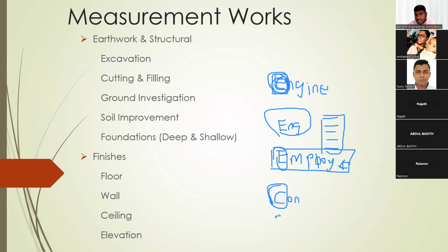If you put a small c, that will refer to other contractors, like subcontractors, nominated subcontractors, or whatever it is. So whenever you write a letter to the Contractor, if you are a client or a consultant, you have to put capital C. If you see the definition in the FIDIC, I said in Clause 1, you go there and check what Contractor is, the definition is given there. When you put capital C, it only talks about the main contract. When you put a small c, that goes to other contractors on the site. So you have to be careful about this when you are writing or talking.